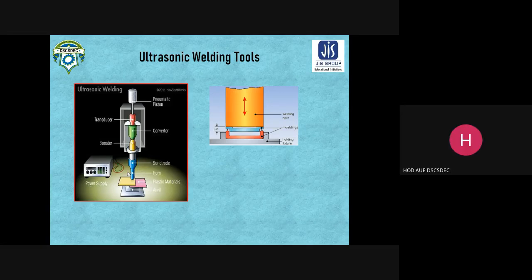Now the question I was discussing was what happens when we do ultrasonic welding for metals. For metals, the greatest hurdle to do welding is its oxide layers, which are deposited on the surface. Ultrasonic welding is a very unique process and goes through a very unique way to disperse these oxide layers. It is very effective.